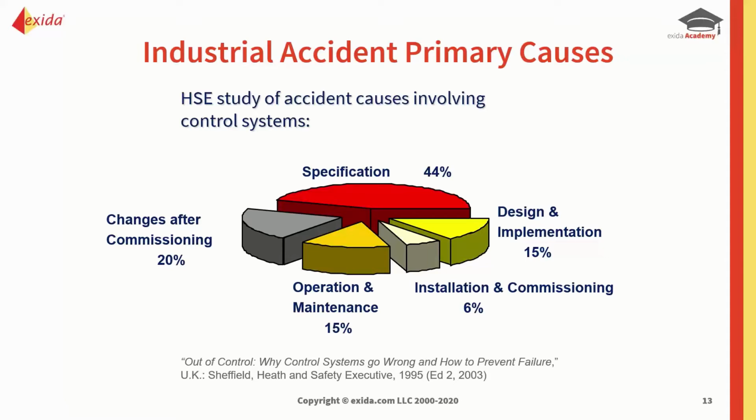But even so, if your specification is right and you still don't follow the right approaches and take a methodical approach to doing the actual design, then you can end up with systematic failures. And when it comes to the application software used in the logic solver, we all know that software is inherently complex, and you can't possibly test for all the permutations. So you could end up with potential systematic issues in the software. What we need to do is make sure that we avoid introducing systematic failures.